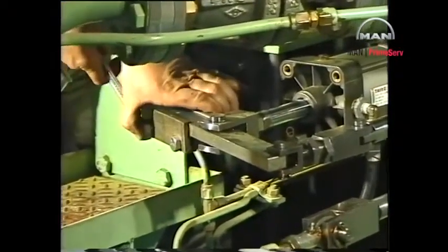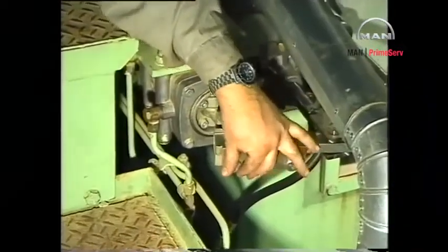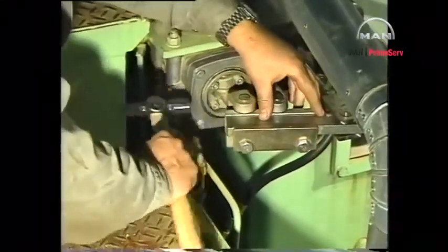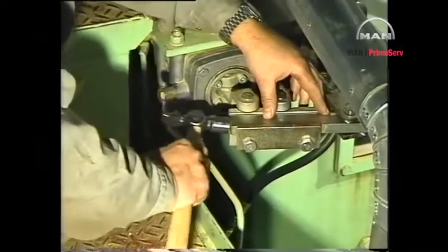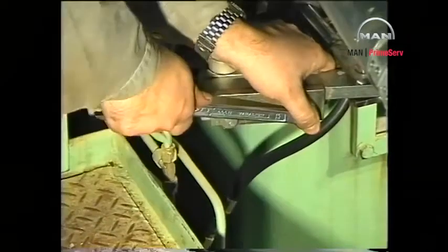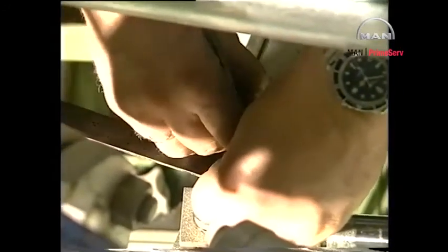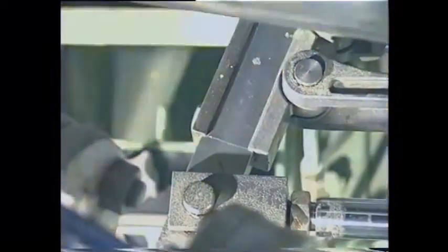In the event that R does not equal L plus X, displace the lever until new measurements confirm that R equals L plus X. When the correct position is obtained, mark the position of the lever and stamp the cylinder number on the locking plate and lever.